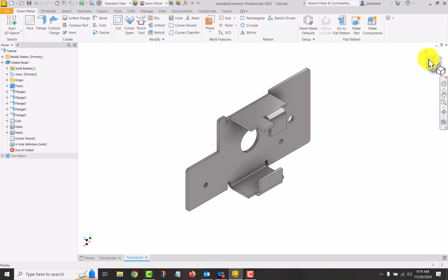And then things like the K factor. A lot of the stuff is based on the type of metal, the thickness of the metal, and then also the machinery that is going to be used to create the bends and the folds. Because every piece of equipment that does the bending may have a little variation in how it works. So those are the kind of things that you would learn in your job based on where you're working at and how the equipment affects those things.